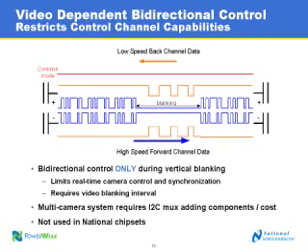And what this really does, it means that you have to have video blanking. So it restricts to systems that do support video blanking. And in multi-camera systems, you lose some of the flexibility for synchronization. And maybe if they need to have something more continuous, they might have to buffer, or they'll have to have some sort of approach to know when they can actually send data. Exactly. It puts a little bit more burden on the other parts of the system to accommodate for the lack of real-time synchronization signals.